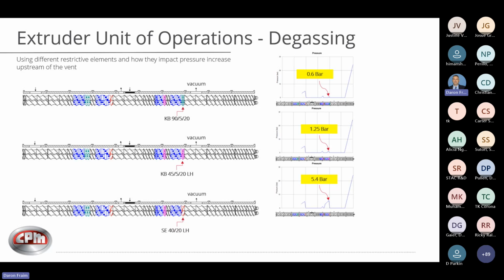So if I'm running a very low vacuum, my negative pressure exceeds that positive. Then what's going to happen is I'm going to pull air through that machine. What's going to take place here, if this vacuum is too strong and overcomes this pressure gradient, guess what? I'm going to draw air through this vent here. I'm not sealing this vacuum. I want to isolate this region here when I draw that negative pressure.